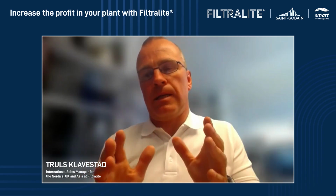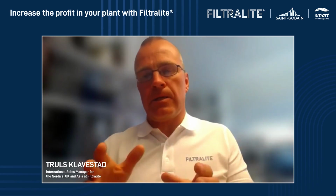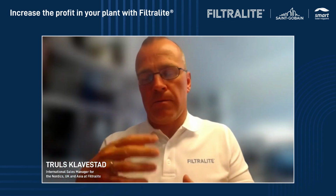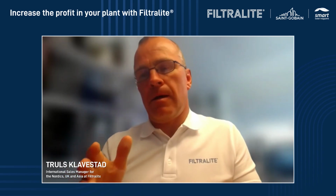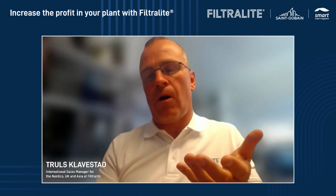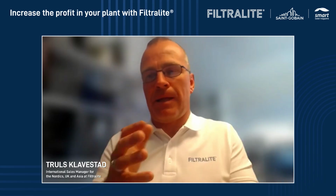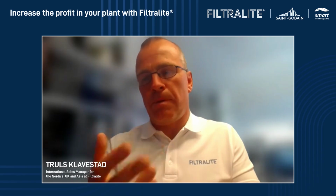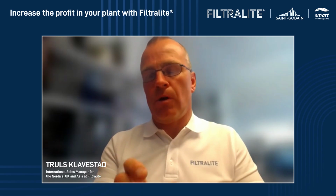But everything about that is for sure always a balance, because the bigger grain size you go for, the higher turbidity or suspended solid you can take. Because it's always a balance. If you go down in the grain size, then for sure the water quality out will be better, but you need to backwash more frequently. So it's always a balance between how often we'd like to do the backwash. That will depend on what kind of recommendation we will give. So everything comes to the grain size.